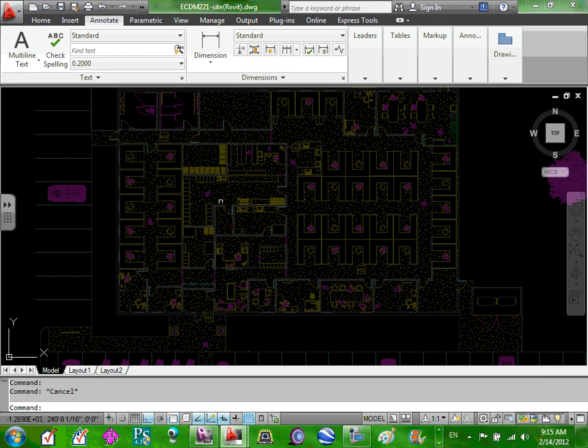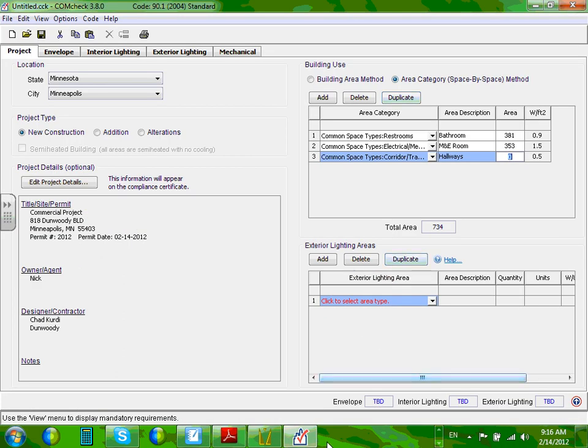Okay. For the corridors, I'll give you a value, guys. The second thing I want you to do: there's open offices, closed offices, general area, dining, conference rooms, and lobby. Let me go back to my software. For corridors, I counted all of the corridors that I have: 951 feet. That includes that corridor and the ones in the open offices. You guys measure them. You should come up with something around 1,000.